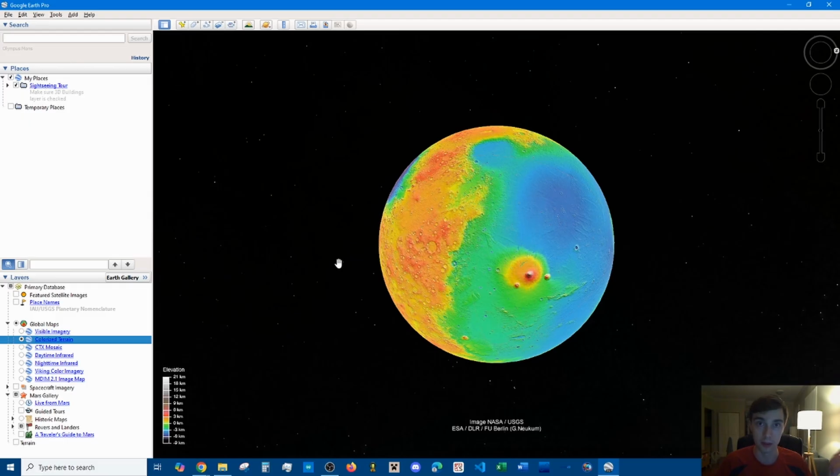The other thing about them is they're dead simple. It is a cold gas thruster. There is no ignition. It is just releasing propellant. The other thing is they're small. They're about this big for a very small one that would do plenty of energy, and they would weigh 10 grams each. I could have 4 thrusters, and let's say one gets clogged up. That means you just cancel the one on the other side. It's very similar to the Saturn V first stage. So these are very much options, and these are things I plan on investigating more in this coming week,